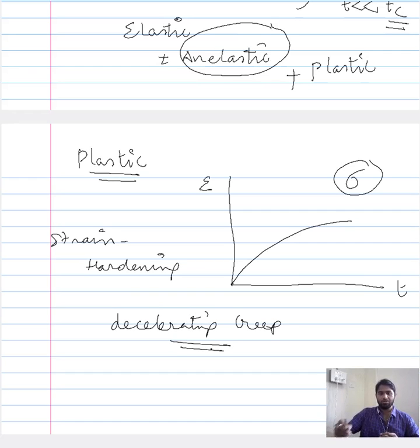So the factor that is responsible for this transient region is the dominance of the plastic deformation, particularly the increase in the dislocation density and subsequently the limitations that are imposed by the increase in the dislocation density for the propagation or the gliding of the dislocation that translates to the plastic deformation. Had we been in the condition where we are allowed to increase the stress, then we can somehow rectify the decrease in creep, but we are in the condition wherein we have imposed a definite mechanical condition, a definite stress to the system. So therefore, the rate of creep decreases in this transient region.